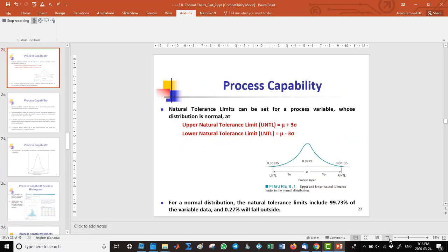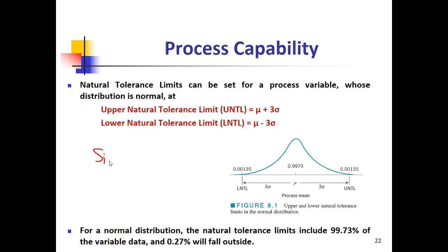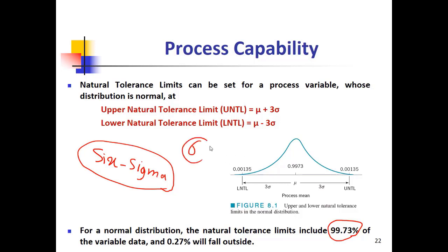But before I continue, you remember that we had the 6 sigma rule in unit 1 or 2, I don't remember exactly. 6 sigma, as I said, is one of the methods that we use to say if my process, my production, is good or not. What does 6 sigma mean? When I have a measurement distribution that follows the 6 sigma rule, 99.73% of the data points will be within minus 3 sigma to plus 3 sigma. What is sigma? Sigma is the standard deviation of the population.